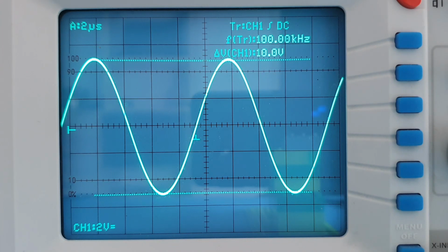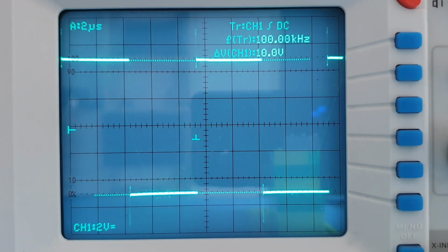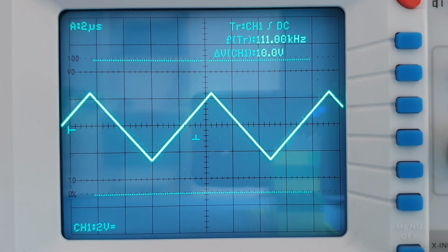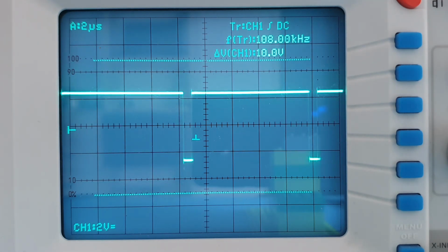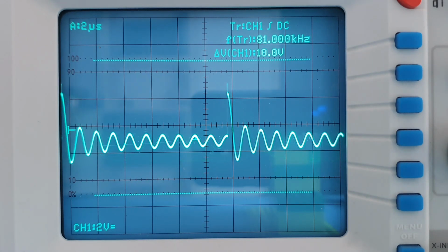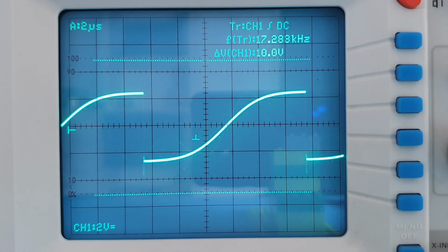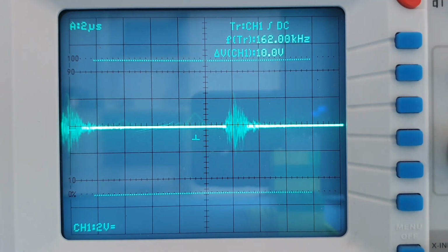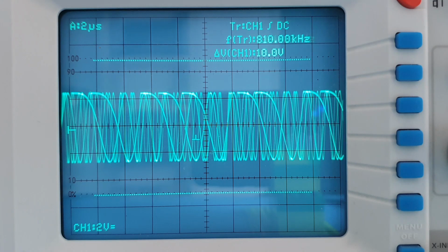Of course, we can also change the parameters, for example a square wave with different frequency and amplitude. Here we have a ramp or a pulse to which we can change the duty cycle. Then we have the arbitrary waveforms, and for this the built-in ones are way too many. You can also upload your own ones through the USB stick.